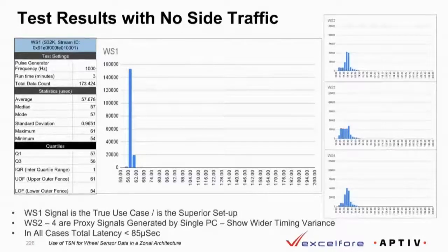And you can see for a major part how the signals are concentrated because they get full priority and they cross the channel in a prescribed time. So that's not a problem there. The latency in the max case is only 85 microseconds. Remember, our end latency budget is always 1 millisecond against which we are mapping. So 85 microseconds clears it by a great margin.